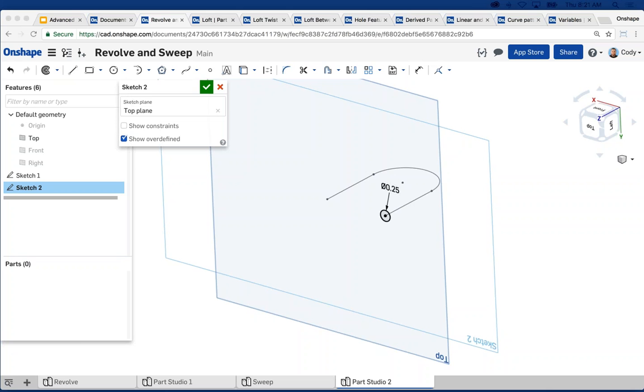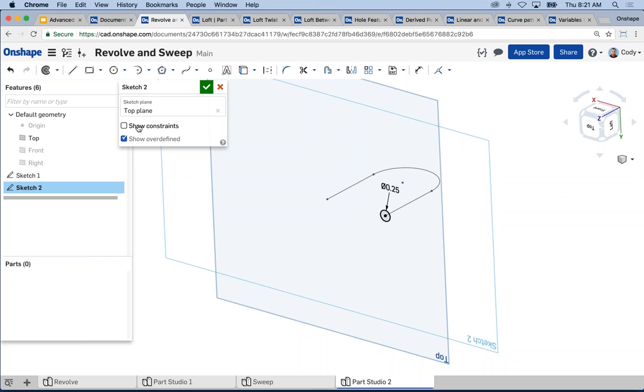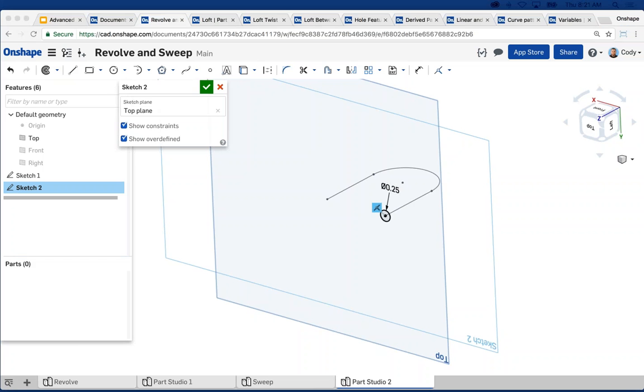Can a profile be attached with a construction line to the path? Sure. Yeah. It's possible to eliminate constraints on a given object. You can eliminate any constraints you want by checking Show Constraints and just clicking the flag and deleting it. So it's easy. Just click the actual flag in the graphics, hit the delete key, and that will eliminate a constraint.